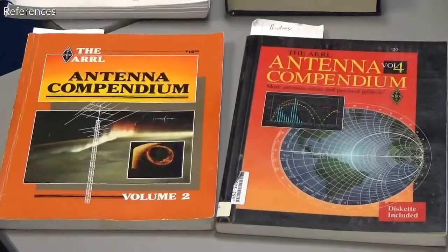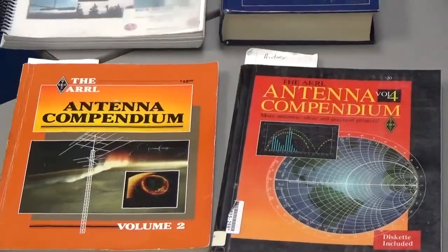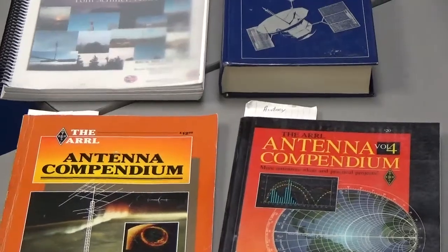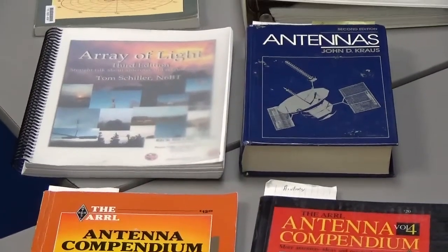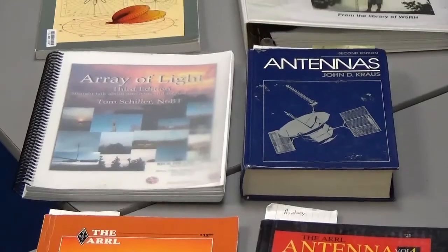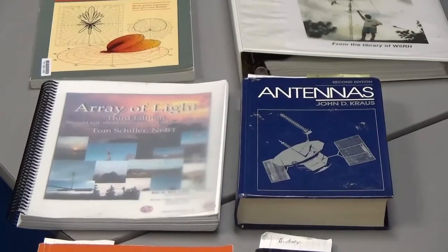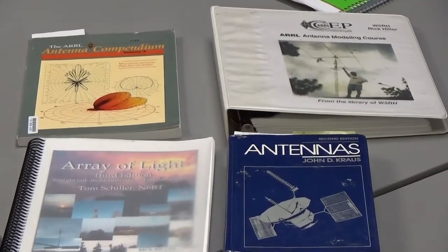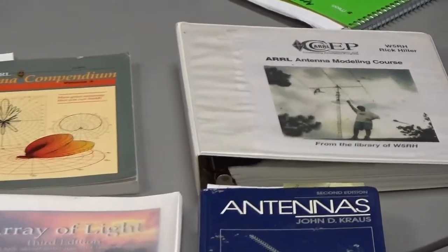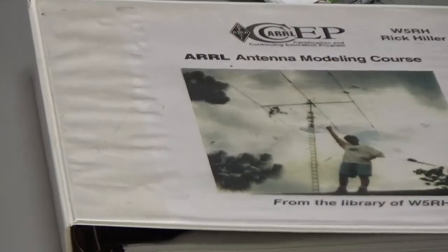Save it as something else, right? So then that builds my little models without having to do much work. Yeah. But it helps you, it's things like looking at how the impedance of an antenna changes as you move it above ground. Take the 20-meter dipole, put it at 15 feet and see what it says.